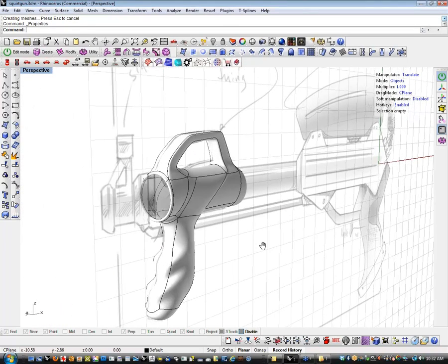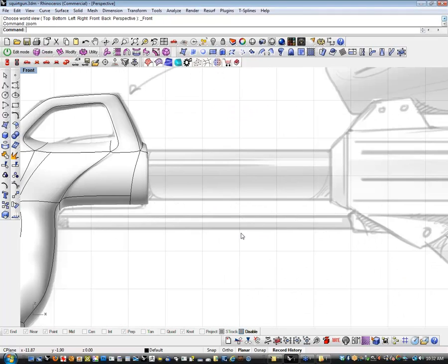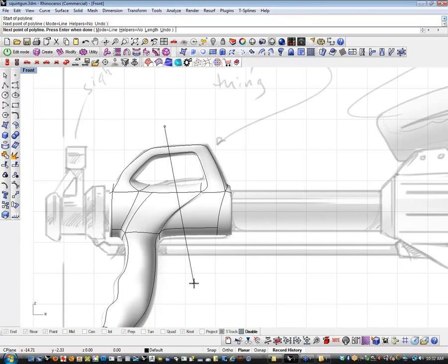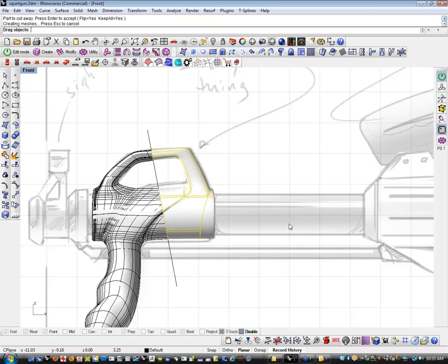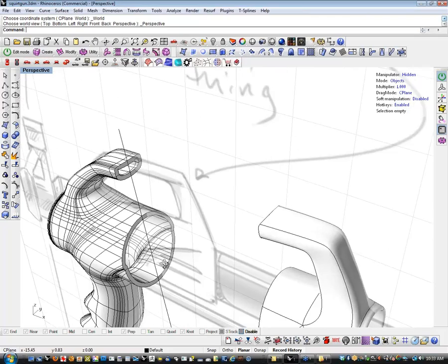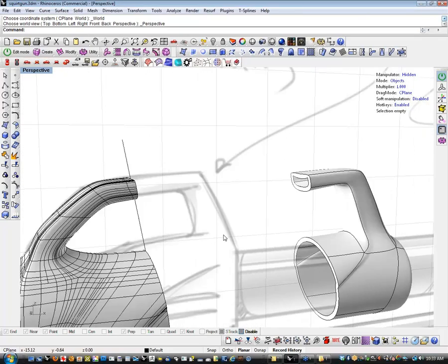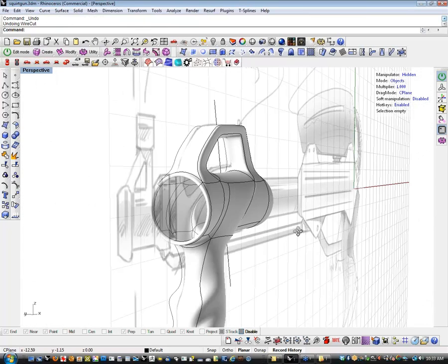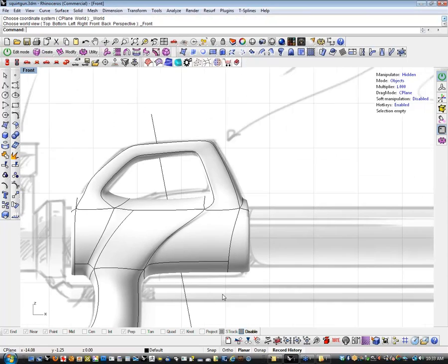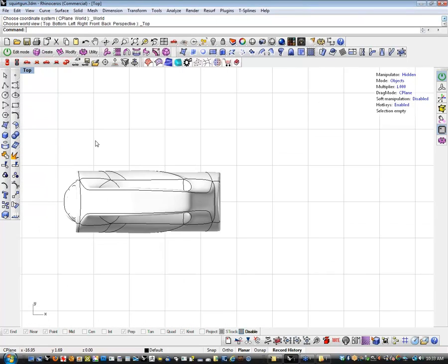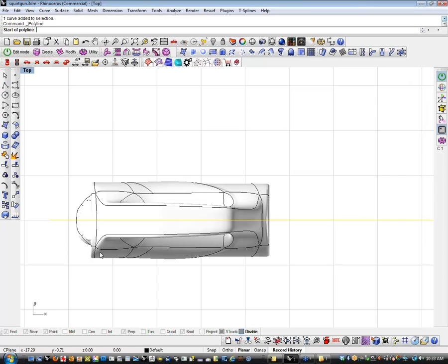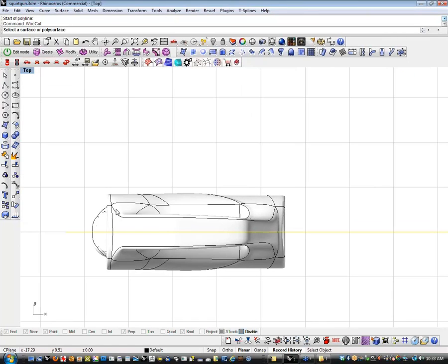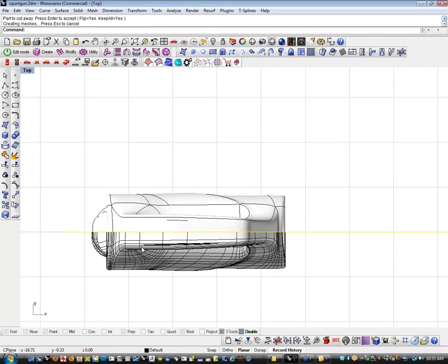But you'll notice that if I wire cut this thing, it does have wall thickness, which is really great because if you're going to rapid prototype this thing, this will go to rapid prototyping all day long. So what I would do is convert this to NURBS, go to whatever view I was going to split this in. In this case, obviously my line of draw would be right down the center, and I just wire cut this and split it into my two halves.